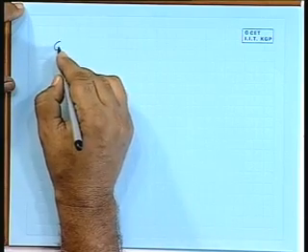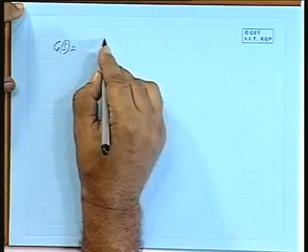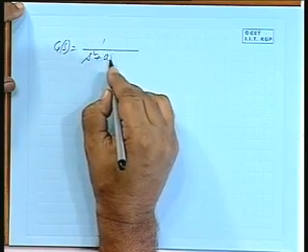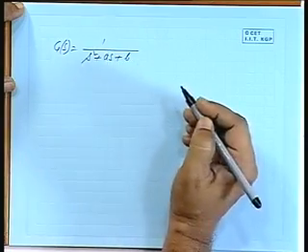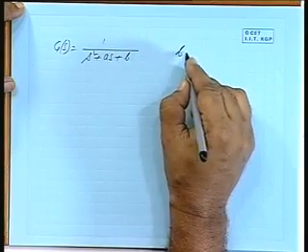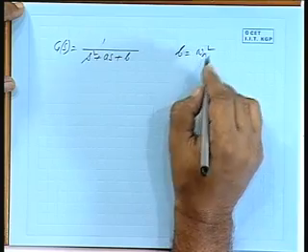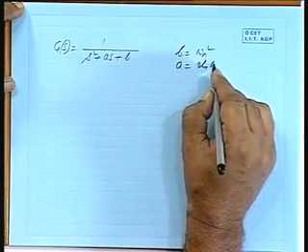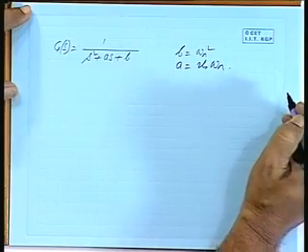Today, we will be taking up the quadratic form in a little more detail. Suppose G of s equals 1 by s squared plus a s plus b. b is the same as omega n squared, just the way we write a as twice zeta omega n.